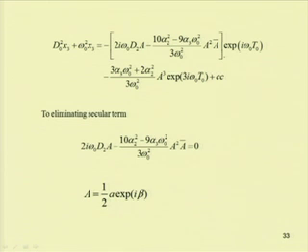Similar to the previous case, here also one can observe that the coefficient of this term should be eliminated to avoid the secular term. So, this is a secular term as the coefficient is omega 0 square. Here the coefficient of x 3 equals omega 0 square, and in this e to the power we have the term i omega 0. So, this will lead to a secular term, because we have to substitute this i omega 0 for this D 0, which will lead to the response being infinity or unbounded.